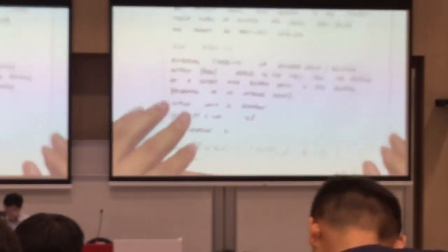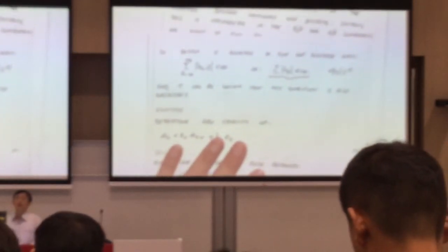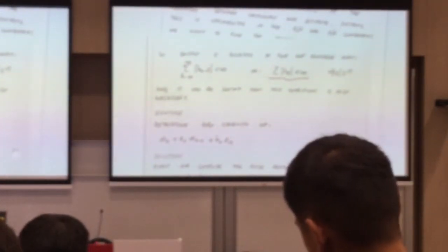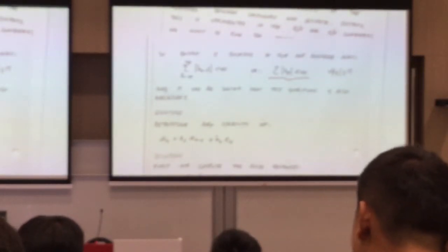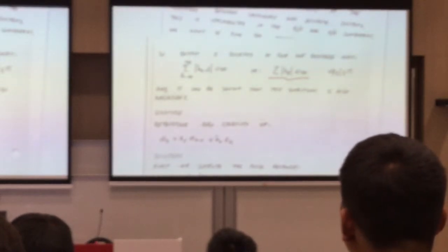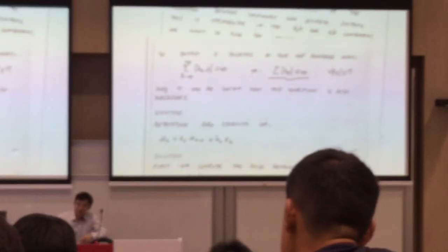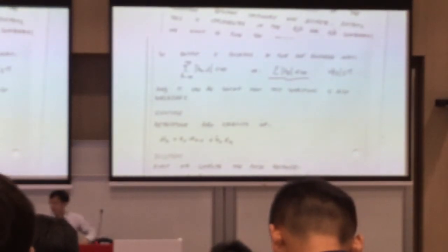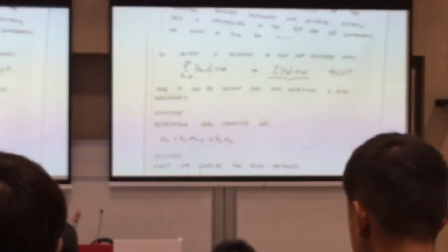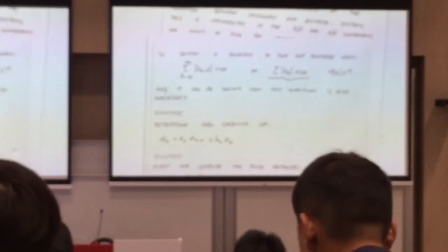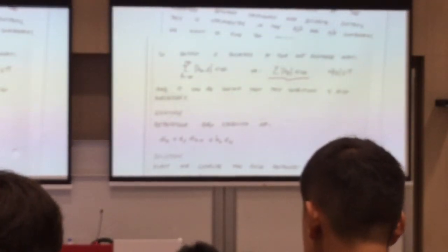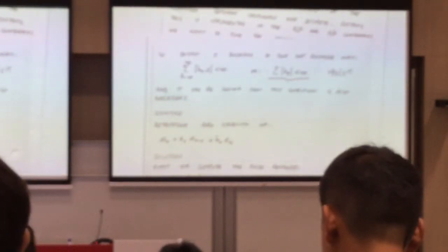And how to do the checking? You want to make sure the summation of hk from negative infinity to positive infinity, you sum up everything together, is bounded. And just now we reviewed the pulse response. Each uk is just equal to hk, right? So we need the summation of your pulse response to be bounded. So the condition is that the infinite summation of your pulse response is bounded. It's not that your pulse response itself is bounded. It is all the summation. Okay?